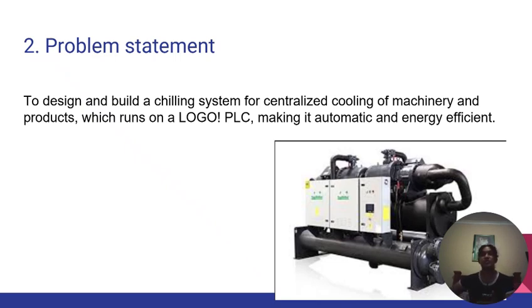So if it reaches 40 Celsius, the pumps would switch on, and when the water or liquid has been cooled down, it would switch back off.